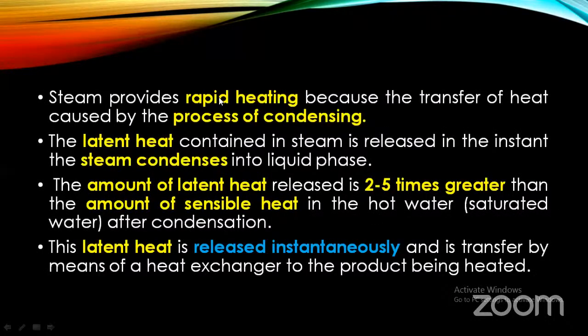So the steam provides rapid heating because the transfer of heat is caused by the process of condensing. Once it is getting condensed, as we have seen earlier, it is the driving force. The latent heat contained in the steam is released instantly, which is much greater than the sensible heat.